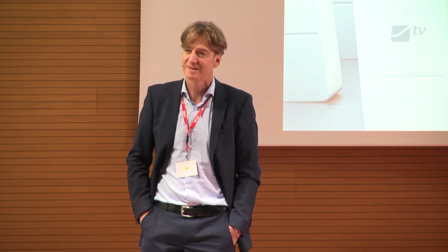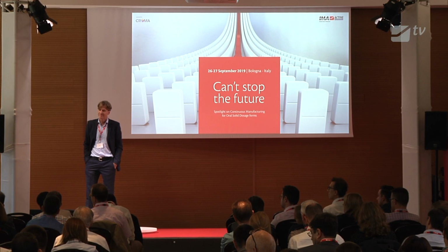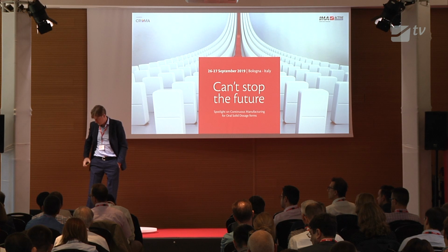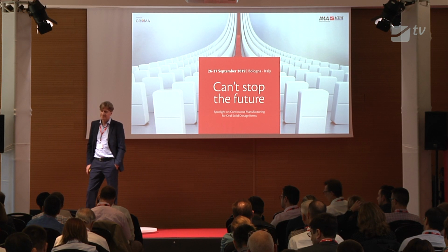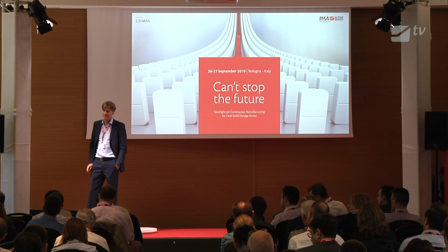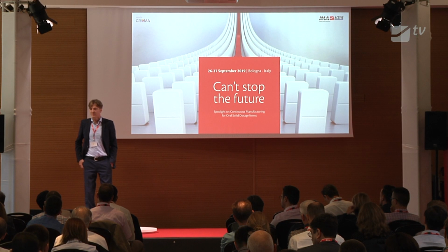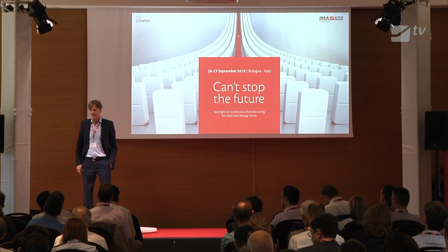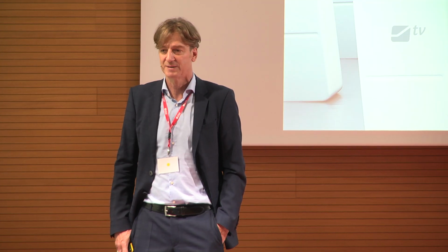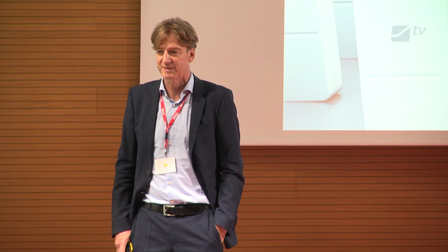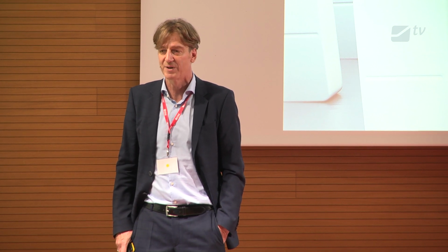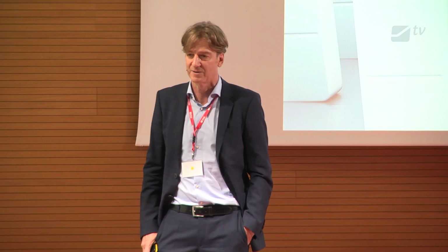Hi. So very glad to see that you have the batch size up to 10K. I would like to understand what is the process capability, CPK, for the entire process. So we have the CPK data, of course, for all the critical attributes, and they are far above 2. The lowest, I think, is 2.0. So it's very robust and constant.